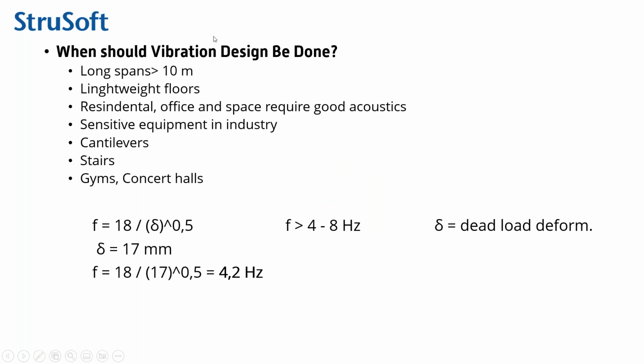Then a few words about vibration checks. In many cases they are forgotten, but you should consider them if you have long spans, or really lightweight floors, residential or office buildings, or anything that requires good acoustics. Sometimes there is sensitive equipment in industry. Cantilevers I would check every time, because they are really sensitive to vibrations. Also stairs, and of course gyms and concert halls with steel frames.